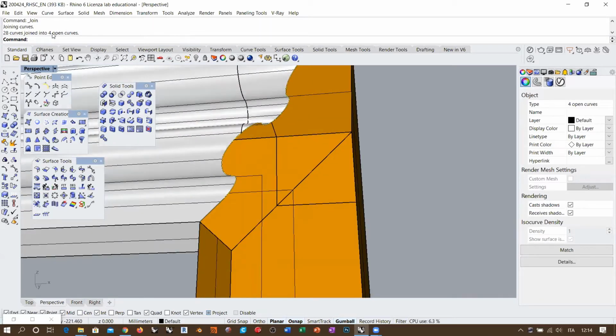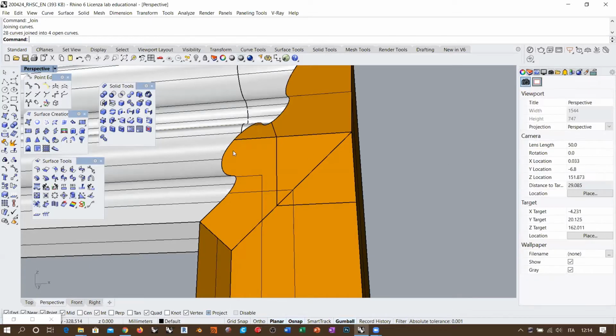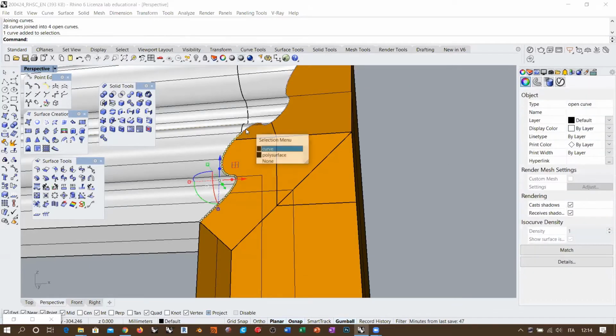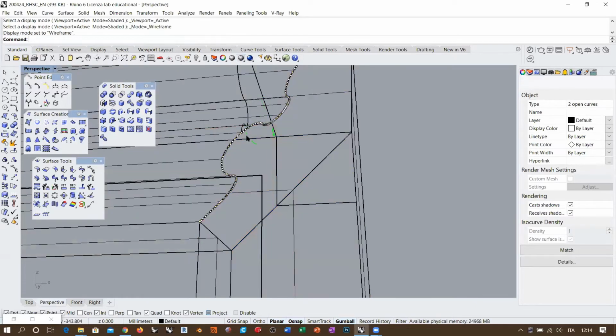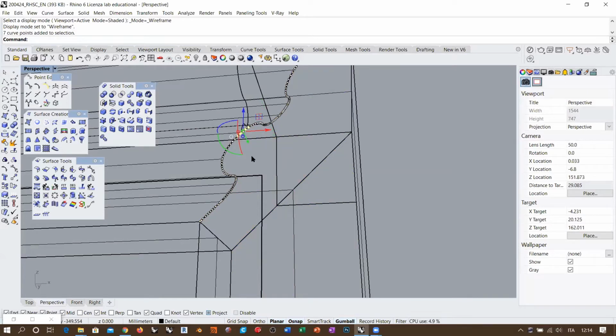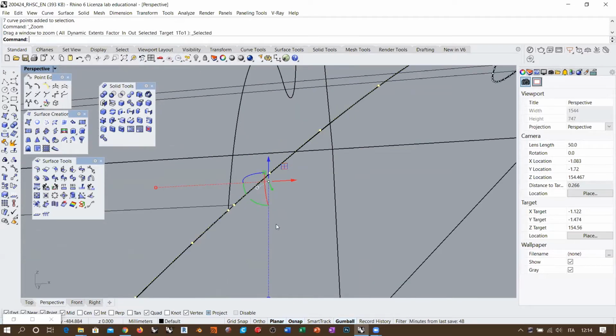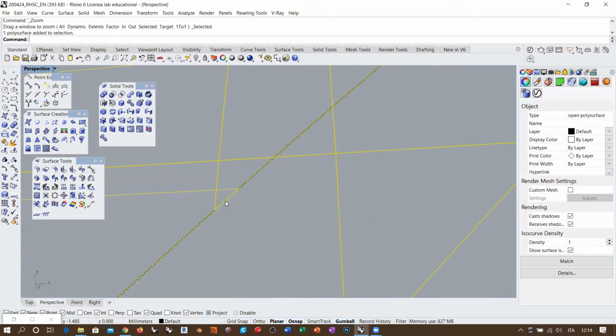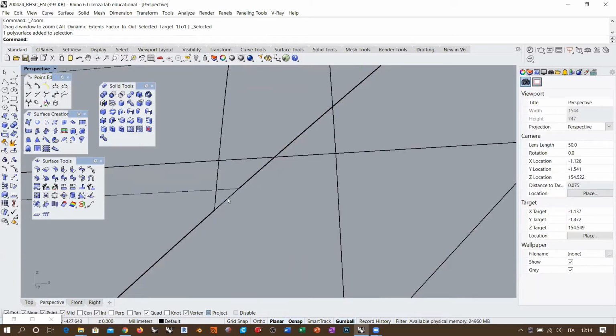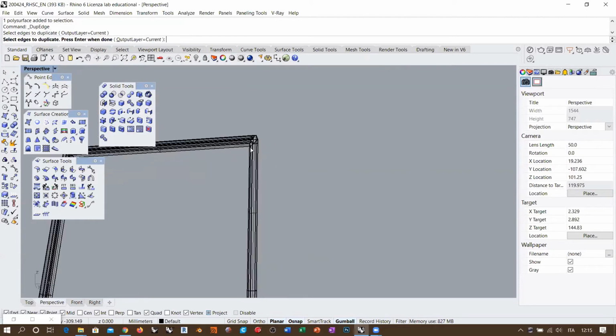And you see that actually I'm getting 4 open curves, and this is interesting. Let's see, curve, and it doesn't join with this one. Now this is absolutely not what I was expecting. Let's go and analyze this detail. I activated the control points and selected only a few control points in order to zoom to selected object. You see? Oh, I missed this edge here. There is a smaller edge because this is a trimmed surface. So there was a trimming that split one single edge at this height. So I also need to extract this little edge, now that I know, also at the bottom.